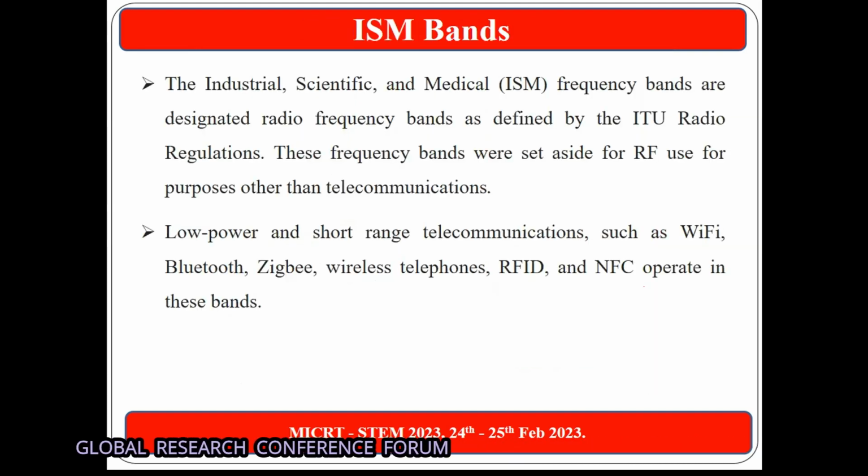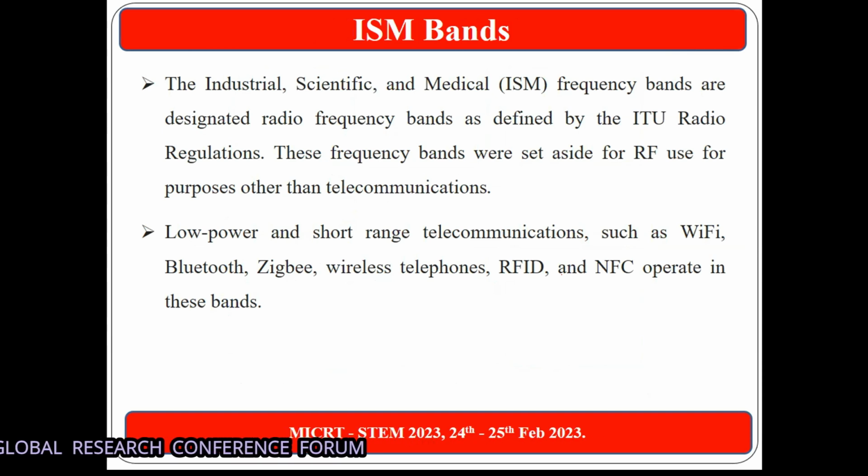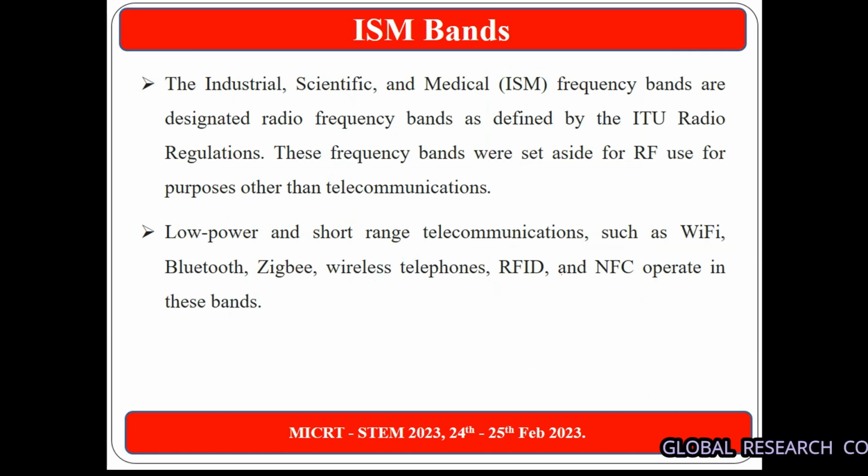Now about the ISM band, for which my title is. Basically the ISM band is nothing but the industrial, scientific and medical frequency band, designated as a radio frequency band by ITU. These frequency bands were set aside for RF use for purposes other than telecommunication. So low power and short range telecommunication such as Wi-Fi, Bluetooth, Zigbee, wireless telephone, RFID and NFC operate in these